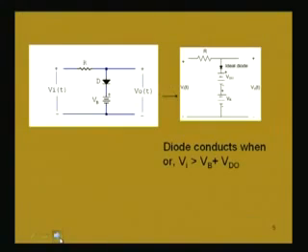So, in this same circuit, we draw the equivalent model for this diode and replace it along with an ideal diode, that is what is done for an equivalent model. If you remember, what we did earlier is that when you want to replace the diode by its equivalent model, we draw the battery showing the drop Vd naught along with the ideal diode.